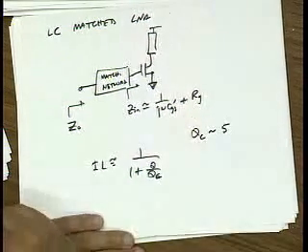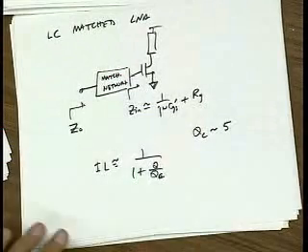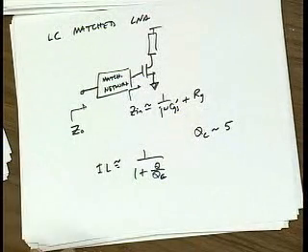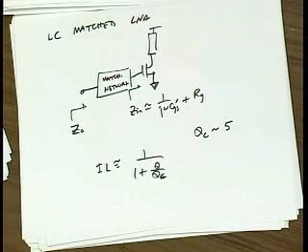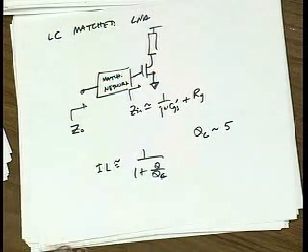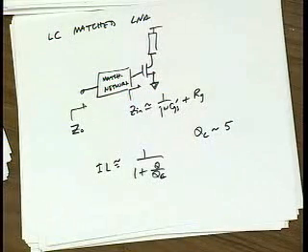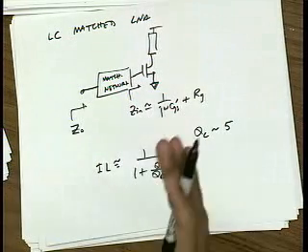So then you say, let me try a 2-stage matching network. You could play games. Maybe you reduce the insertion loss down to 2 dB, but you're still stuck. You have this big loss in front. And you definitely need an impedance match, because remember, you're trying to design a component that terminates a transmission line. So you'd like to have a constant impedance versus frequency, or at least in the band of interest.